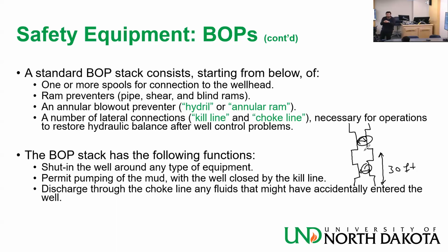It will happen slowly, there is friction, etc. But the joint won't. So I need to have that pipe ram open. But in order to have the well shut in, I need to have another pipe ram higher up closed. That's why you see a lot of rams in the BOP stack.